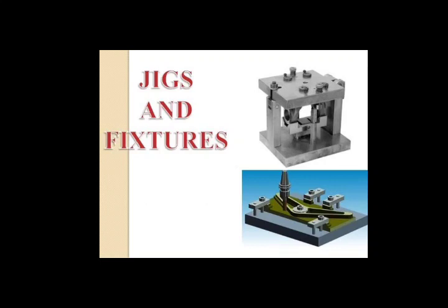To eliminate this situation, the tool designer will provide a foolproofing pin on the required side, taking into consideration the square part and the tapered angles of the workpiece. The foolproofing pin will obstruct loading if the workpiece is wrongly loaded, so it is impossible to load the workpiece in an incorrect position. That is the advantage.